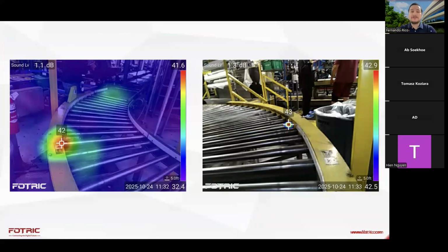In the same manner, I invite you to think how much time it would take to use a listening-only device to check bearings, like on this conveyor system. These systems start failing and produce ultrasound from damage in the bearing, or problems with lubrication, for instance. Try to imagine aiming the listening gun at one, two, three, four, five, and it continues for each of them.